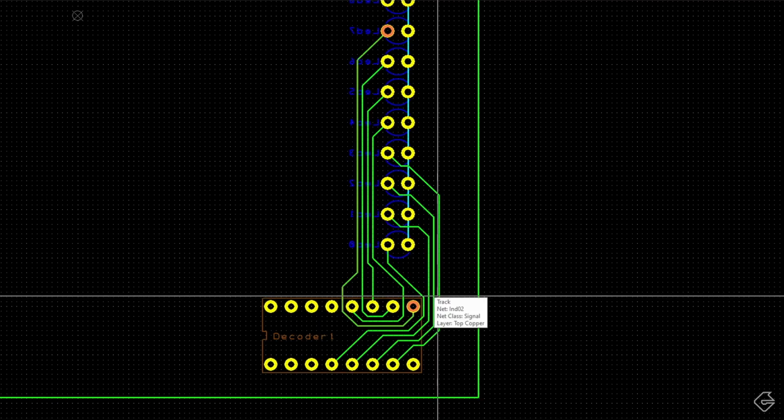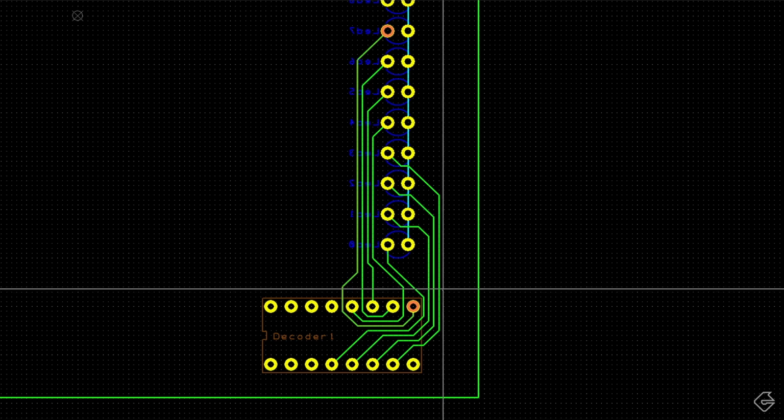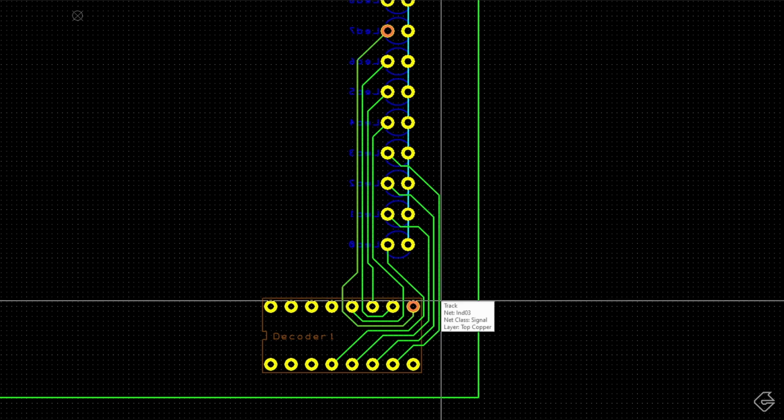The only consideration we have to be mindful of is the amount of current going through our traces. Right now, we're not pushing any high current. We will later, of course. We're going to get to the high current LED drivers, which is why we're doing it at the end. But for now, these are just signal traces. So these traces are 0.2 millimeters thick, and they have at least 0.2 millimeters of spacing between them. I think there's actually a little bit more in this case.